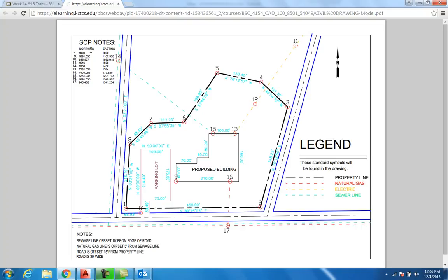So on this one, northing means that is your Y direction from that origin. Now, like the single zone Kentucky state coordinate plane, it is the lower left tip of Kentucky out toward the Paducah area. It's the lower left tip. And in this, if you use the south, where you're using the split of Kentucky, it is in the same location. But now the northern half is just a little bit different. But on this one here, what we're saying is northing would be your Y, easting would be your X.